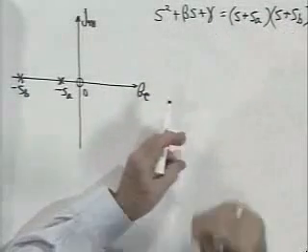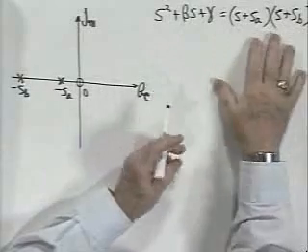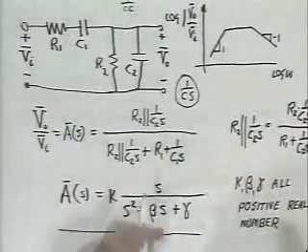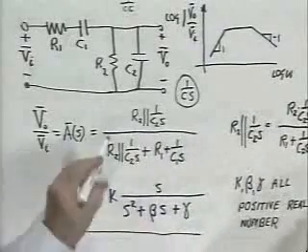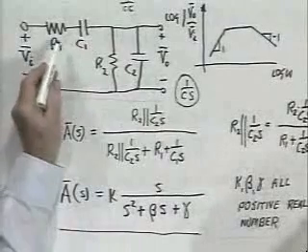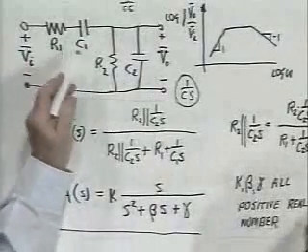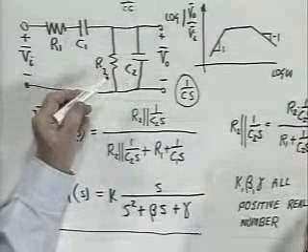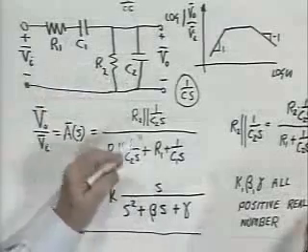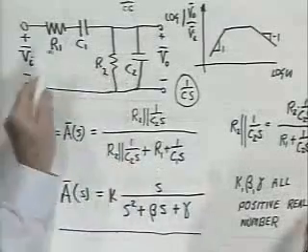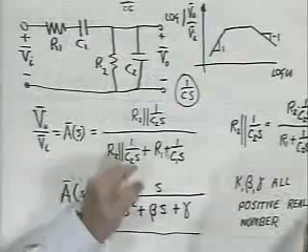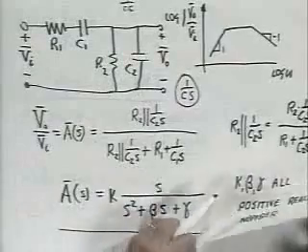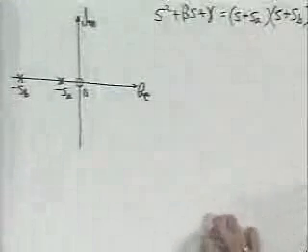You may ask, well, this is a quadratic, why can't it have imaginary roots? It will turn out, if you work through the algebra and crank out what this transfer function is, that for all possible values of these parameters, I'm going to end up with two real roots of the equation. It is not possible in this circuit, in spite of the fact that it has two energy storages, to get a quadratic with imaginary roots. You just have to take that on faith at the moment.